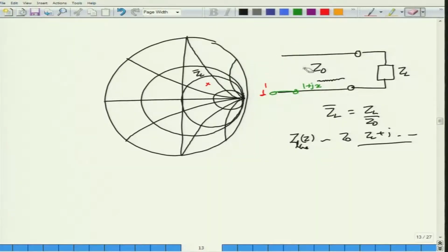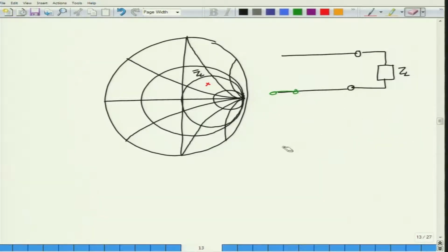Instead, we recognize that a Smith chart is as good an impedance chart as it is an admittance chart. So we simply realize that I can work with admittances. Instead of talking about ZL bar, I talk about YL bar at the load side, and then I move YL bar. At some plane I would have obtained YL bar prime, the transformed admittance, which will have a real part equal to 1, but some imaginary part equal to jB, where B is the susceptance. So I have moved it such that I land on the transformed admittance of 1 plus jB.